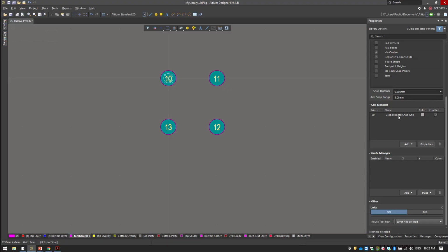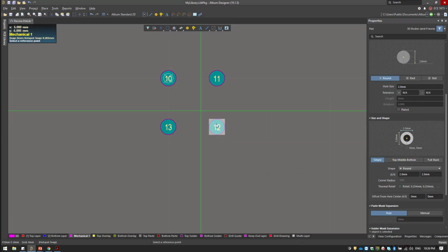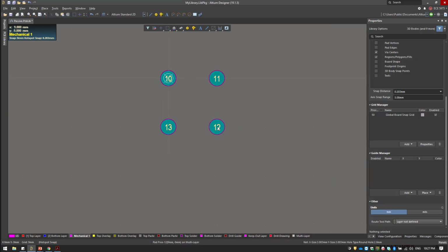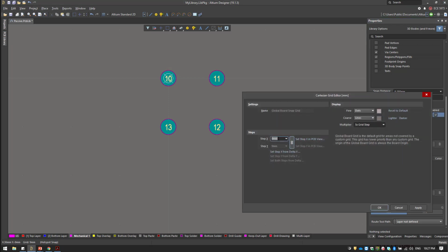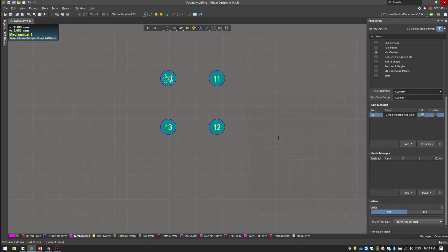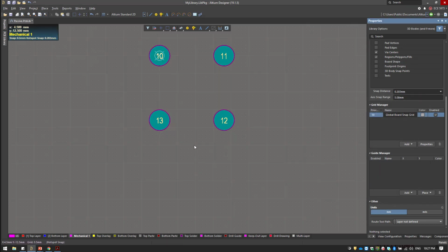Now first of all, let's change our grid to 6mm. Very easy, very simple. Copy this pad, and now Ctrl V, as you can see, it's off grid. So the easiest way is you can change the grid back to, let's say, 0.5 millimeter, because you have 9 millimeter and you need to position this at 4.5, which is the center point between these.